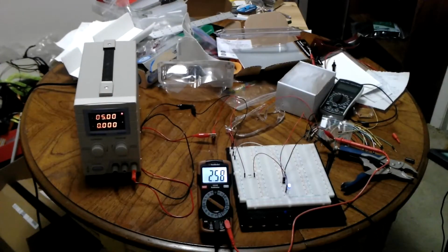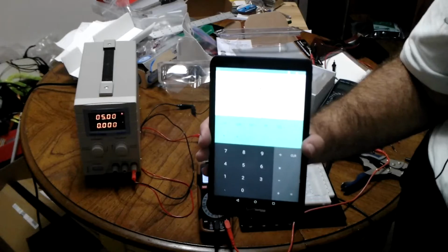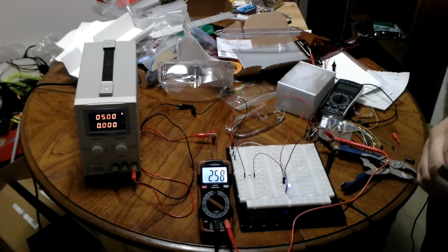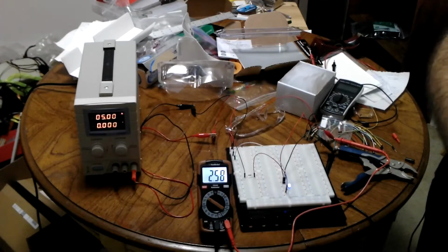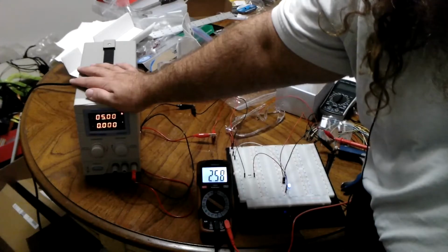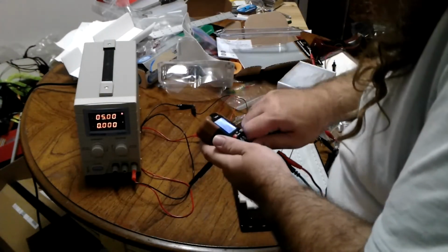So 2.58 divided by 239 divided by 1,000 divided by 1,000 comes out to be about, I don't know if the glare's too much, about 10,000 ohms. In fact, it's 10,794.979 ohms. There are some inaccuracies built into using a cheap Chinese power supply. But that's a simple demonstration of Ohm's law.